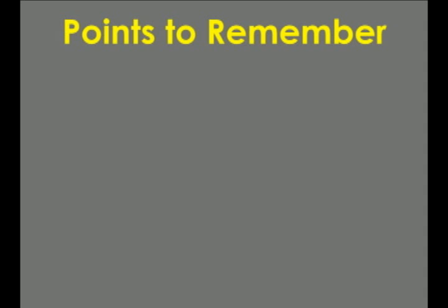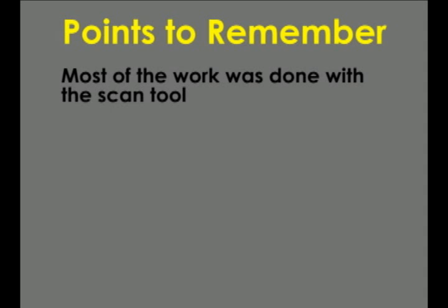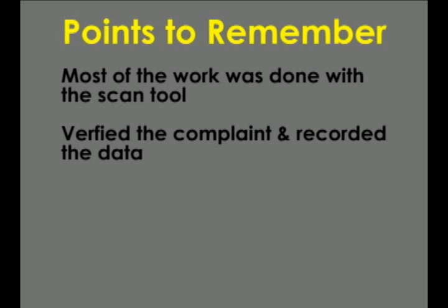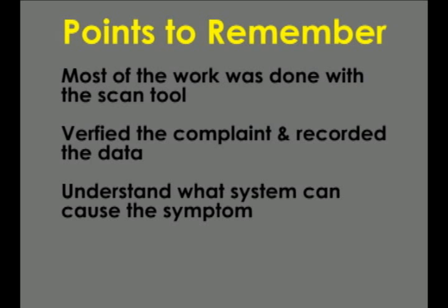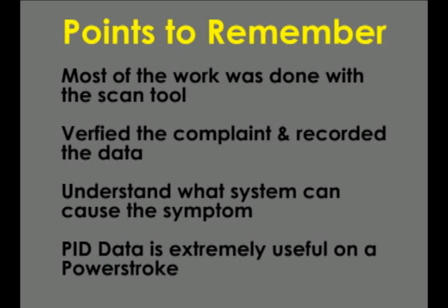It's important to note the procedure taken to diagnose this vehicle. Most of the work was accomplished from behind the steering wheel with a scan tool. While we verified the complaint, we recorded the data. We had a good understanding of what system can cause the symptom, and we chose and interpreted the correct data PIDs, as this information is extremely useful when diagnosing a Power Stroke with no codes.